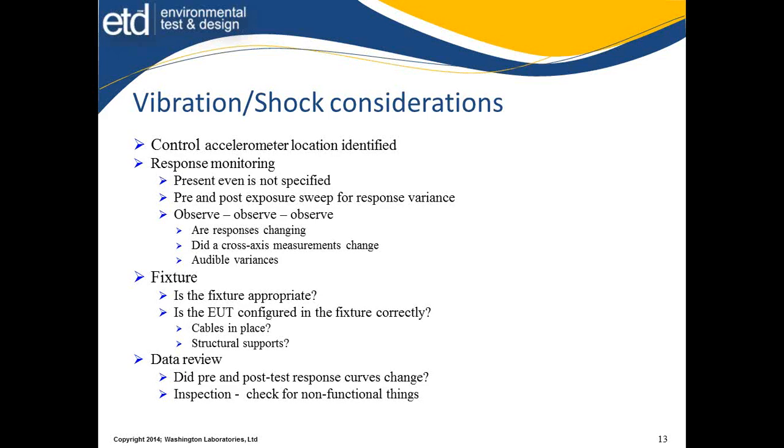Do we hear things going on? Quite honestly, a lot of people don't like the sound of the vibe table going on, so they don't even listen. They shut down, put earplugs in, etc. But quite frankly, if a unit starts coming loose at the fixture, you may hear some significant audible changes, and it might tell you I need to look around to the back because something went wrong here. So don't hesitate to be observant. You need to be clearly observing what's going on and following it, seeing that it's not something different than you planned. Or is the plan to find it fail?